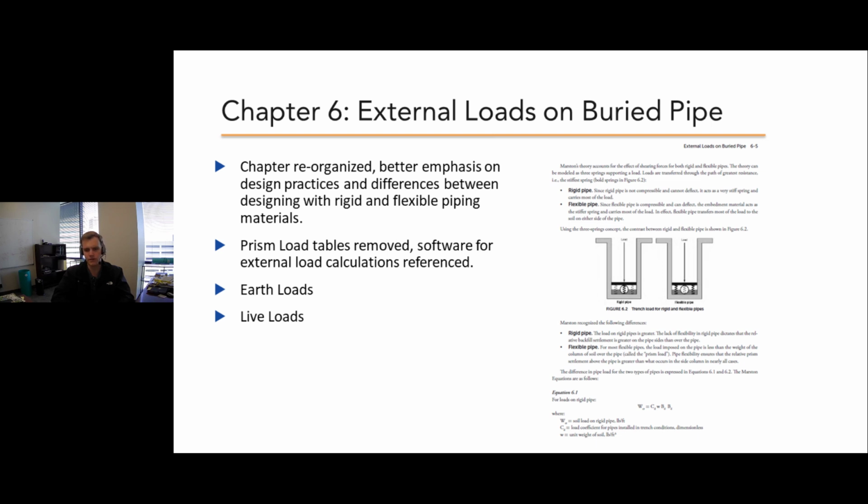And the main difference really is that for rigid piping materials, the pipe itself isn't using the surrounding trench for support, and so the majority of the soil and external load weight is being supported by the pipe material itself. For flexible pipe materials like PVC and ductile iron, the pipe has that flexibility there that allows it to use the soil arch to support the pipe. So that force downwards from the external load is being distributed throughout the soil surrounding the pipe with flexible pipe materials.